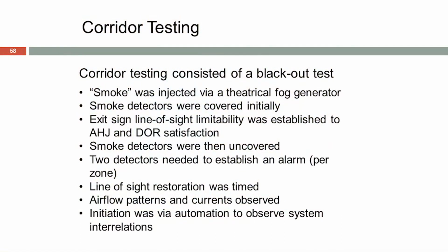Any questions on the ballroom? Okay, so again, we didn't feel the need to use any heat. Our little booster fan on top of the smoke was enough to just get the smoke up into the plenum instead of it just falling and laying. Because again, it doesn't have its own heat rise and buoyancy effect that you're looking for that you'll see in a natural fire.